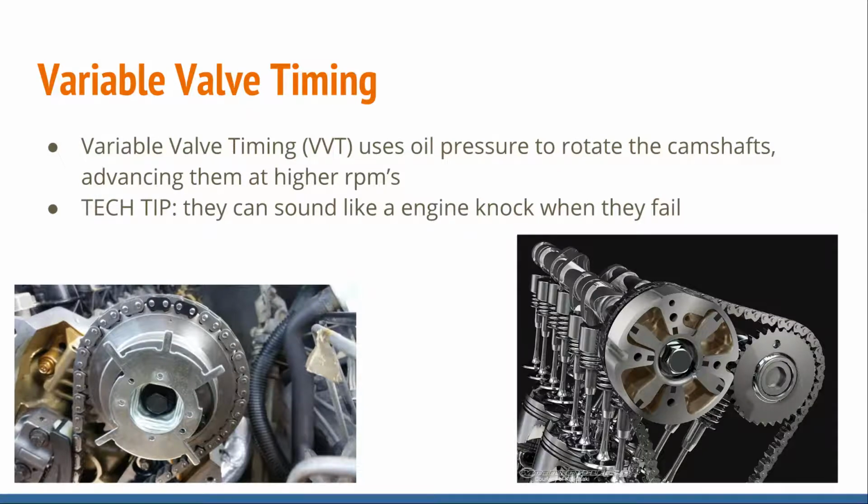Little tech tip: when those camshaft gears, VVT gears, also known as camshaft phasers, start to fail, they can sound like an engine knock. And you could swear you've got an engine knock when in fact you've got a phaser failing.